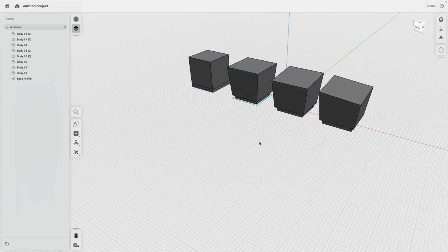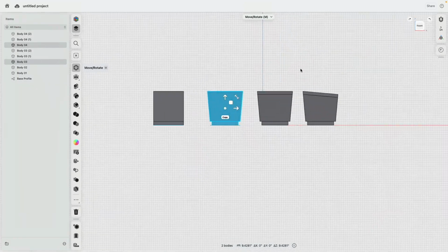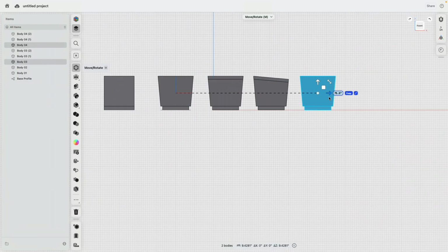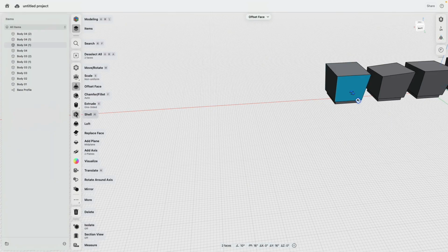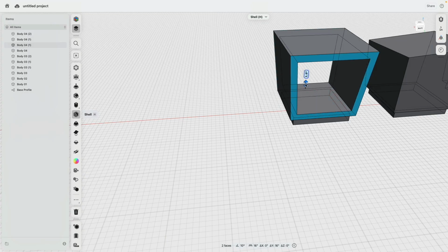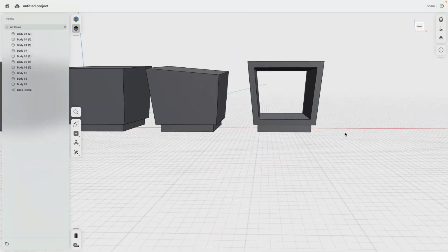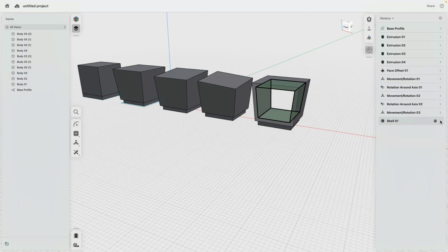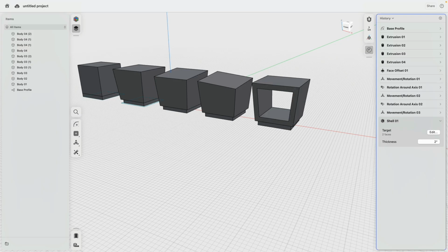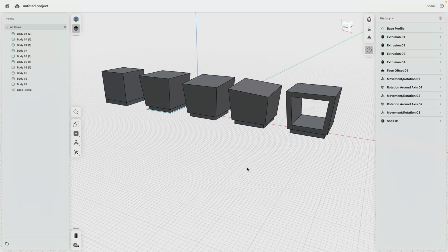Okay, so you see through very simple extrusion and then rotating faces, we already created 3 different variations out of a block. Let's make one more. There we are. Let's make a copy, bring this over there, because here I will explore the idea of, well, what happens if we shell this, actually hollow this out. 1.5, so it has a good thickness. That seems to be too thin. We can make this a little bit bigger, say 2 inches. Yeah, that's fine. That looks good. Okay.